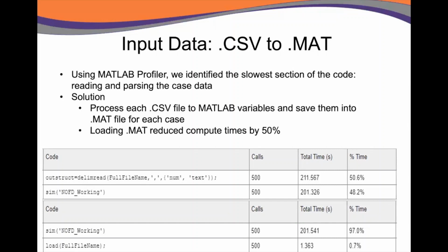To solve this, we process each CSV file to MATLAB variables and save them into a .mat file for each case before running the function. Loading the .mat reduced compute times by 50%.